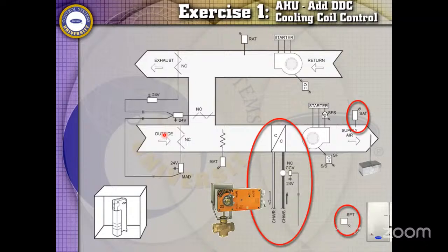I also got chilled water and hot water coils in here. I could also instead have a gas burner, or I could have an evaporator coil connected up to a compressor for a DX system. But right now it's a chilled water valve in my particular example. That chilled water valve must be modulated for VAV. It cannot open close. It has to modulate. And specifically, it modulates based on a temperature in the supply duct.